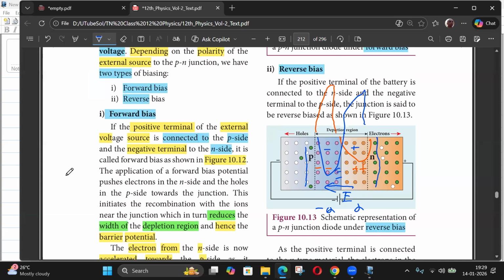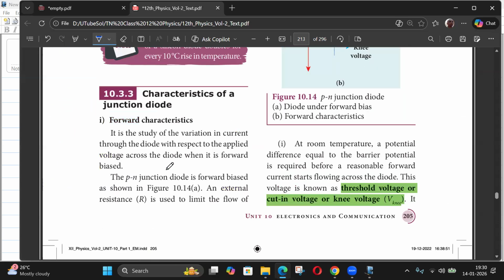Silicon will have 4 covalent bonds. In addition to that, there will be free electrons if it is phosphorus, or free holes if it is boron, the impurity which is added to the silicon. This silicon here, and there will be impurities in between. So for these free electrons and holes to move, this voltage is enough. But if this electric field is strong enough, it will actually break these covalent bonds and produce free electrons and holes. So there are two ways in which it can happen.